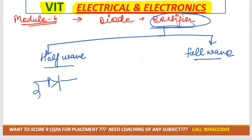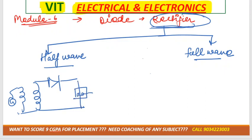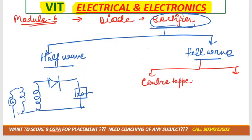We'll have a single diode, we'll have a transformer, and then we'll have a load connected, something like this. And the full wave is further divided into two categories: one is the center tap rectifier, another one is the bridge type rectifier.